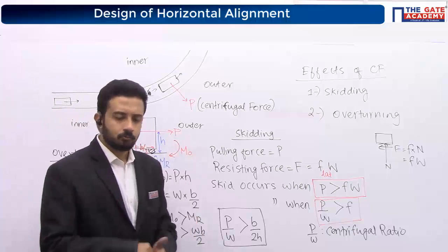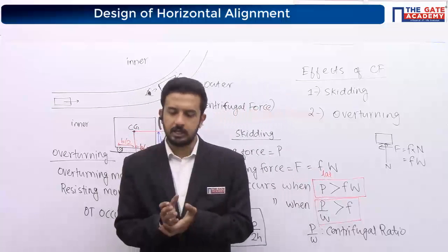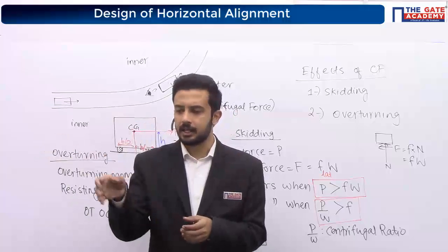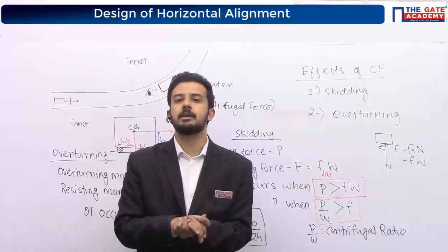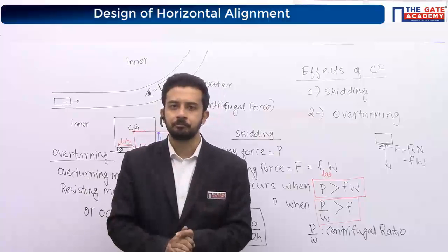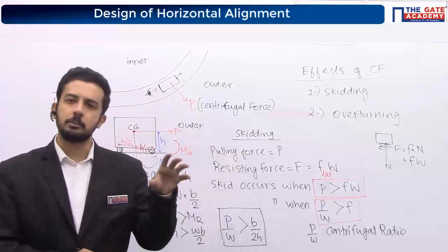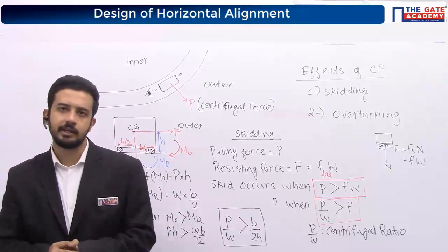What about H? Can you decrease the height? Not possible. We need some height, definitely. Our roads will have speed breakers, bumps, humps, so we cannot reduce the height. We need some clearance. Our roads are designed for heterogeneous traffic, so we have to limit the speed sometimes. We can't decrease the H value.